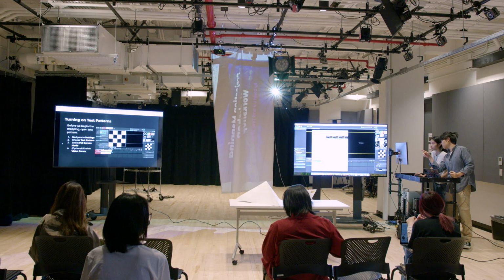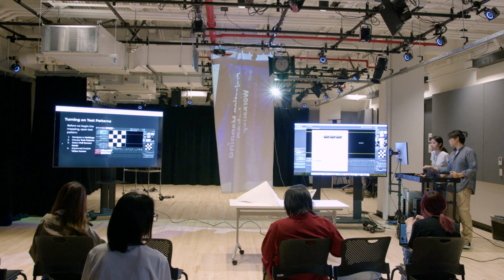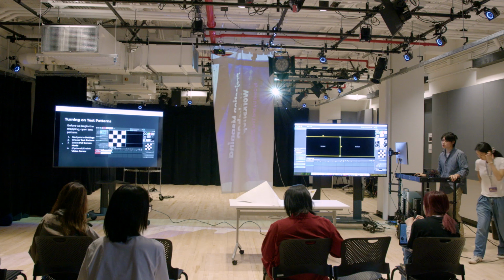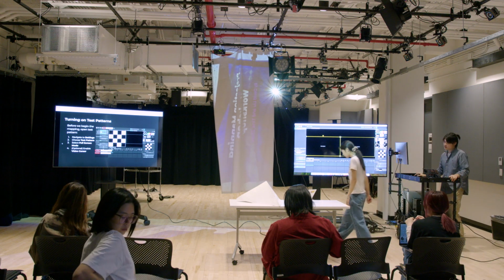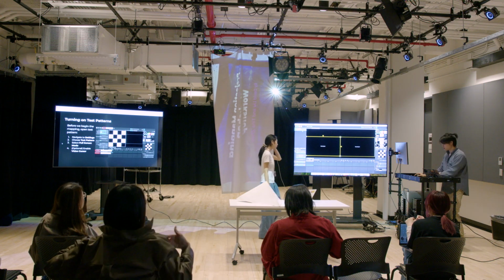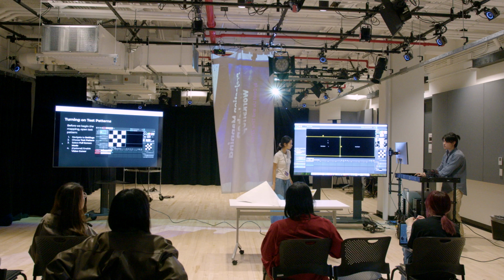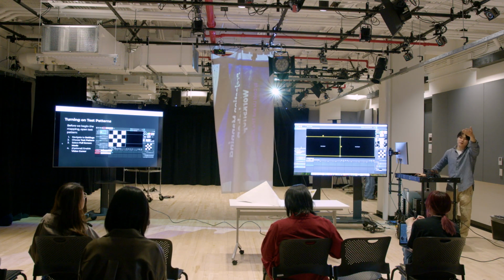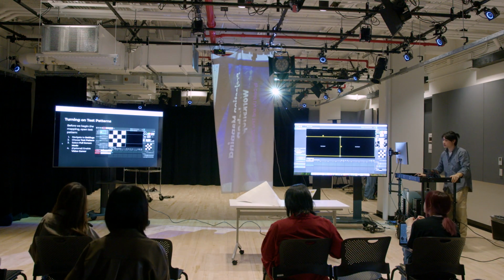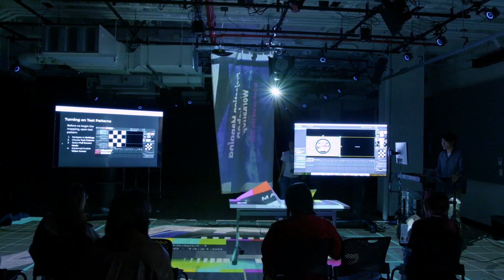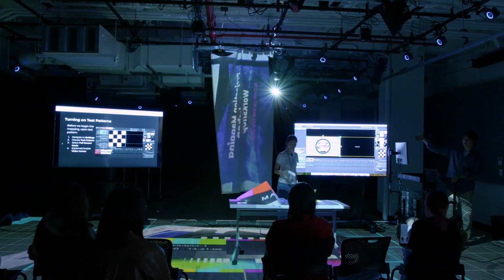I think it's all correct except for Optima. I think it's correct. Yeah. Okay. So now that we have it all set up, we're going to come back to the outputs page. As you can see, I've already created 2 video outputs, but if you need one more, you can just click this icon to create another one. In this case, we're not going to need it. Output number 1, I've specified to HDMI extender, which is the Epson projector right above you. What I'm going to do is toggle on show test pattern and come to outputs and full screen mode. As you can see, the projector is receiving the signal correctly.